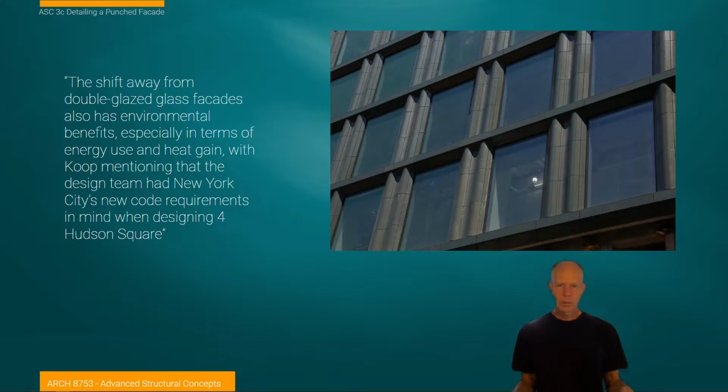It also reduces the amount of glass area, which reduces the solar gain, which means that we need less energy for cooling systems. And you might say, well, won't that add to heating in the wintertime? But typically what happens in northern climates is that the solar gain from an exposed window never achieves more energy input than it loses through thermal radiation back out again. So we really can't add windows to a building in a northern climate that will actually create energy efficiency.